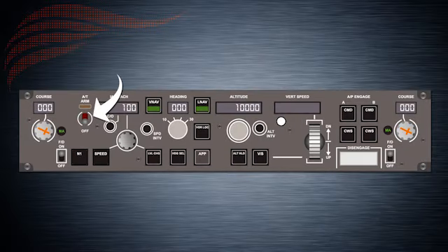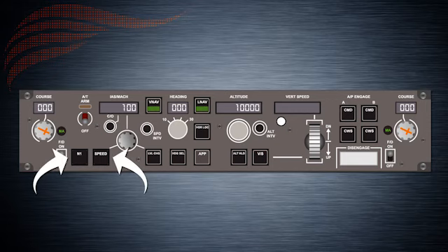Auto throttle is armed on the MCP. From the MCP, not only is auto throttle armed for Autoflight modes, but there is also direct control of thrust through the speed and N1 modes on the left portion of the MCP. When in N1 or speed modes, auto throttle is not controlled by any other part of the Autoflight system apart from its normal communication with the FCC, thrust levers, and therefore the engines.